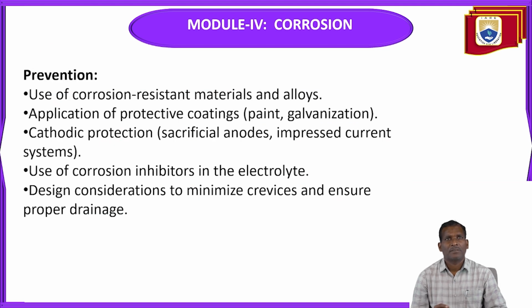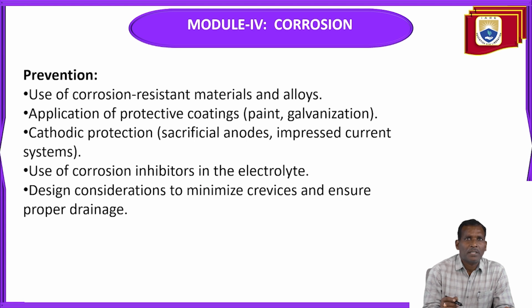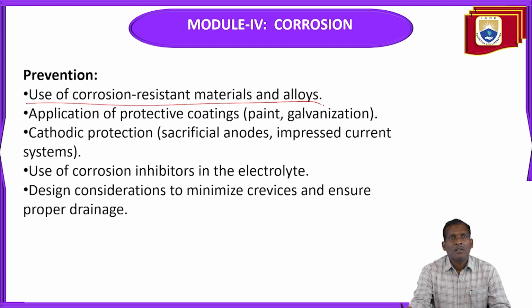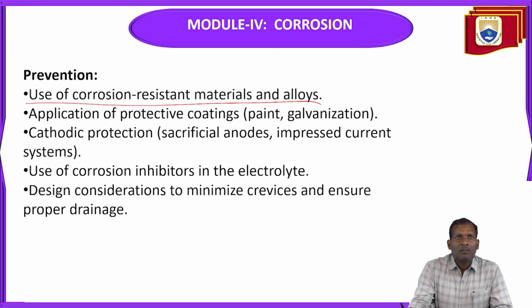How to prevent this wet type of corrosion? Use of corrosion resistant materials and alloys. Application of protective coatings like paint and galvanization.